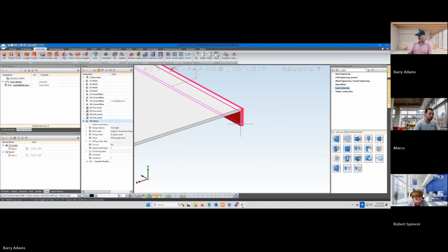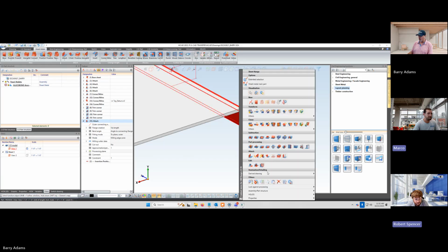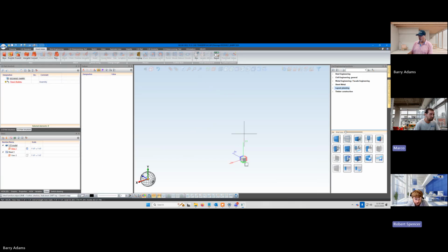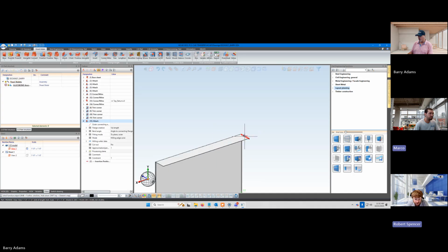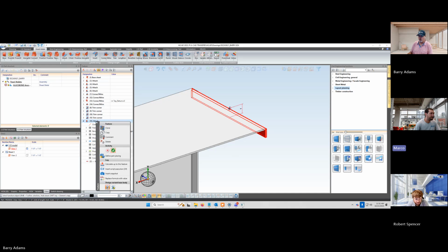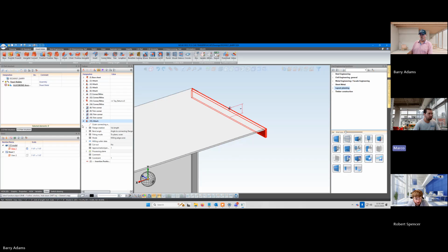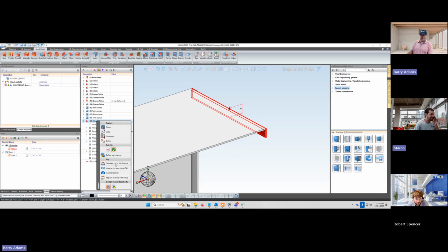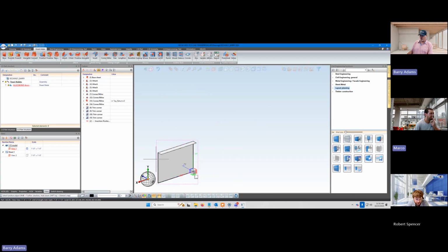Shift. And then delete. Delete. Nope, that's the whole part. You got to go to the feature step to delete. You only want to delete that feature. Feature step. Delete this one, corner miter. Nope, you want that one. You just constrained it. You just did some work on it. You want to delete the flange. So right click on the flange. This one? And say delete. Ain't nothing says flange. Attach flange. This is highlighted, so it's this one. Copy that one. Okay. So do this one first.